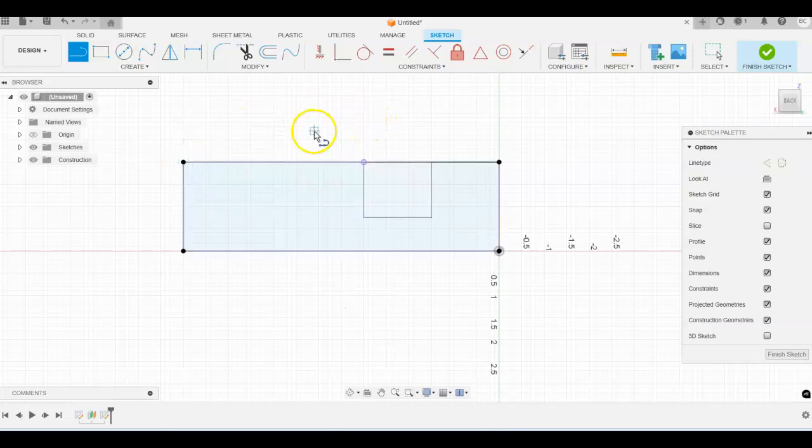Now, we're going to follow the same logic here when we draw this. So I'm dimensioning this the same way, and I'm going to assume that because the top view shows that that is a 45-degree angle, hopefully this will work out, but we'll double check to make sure that it does.